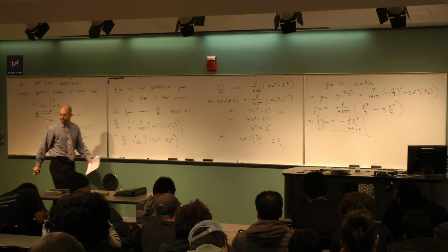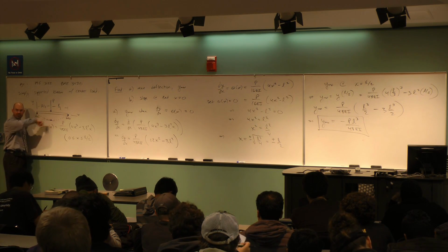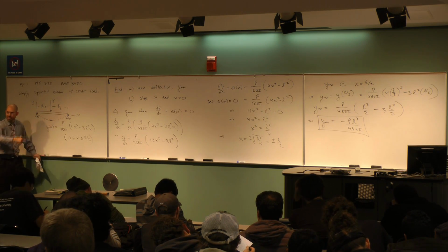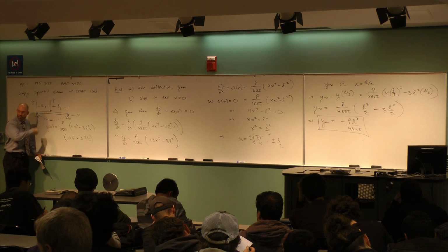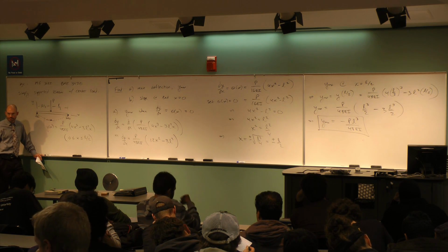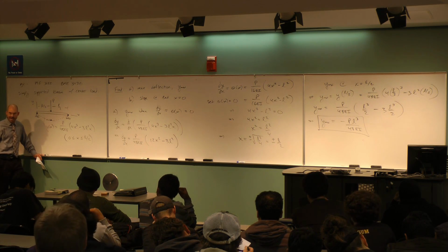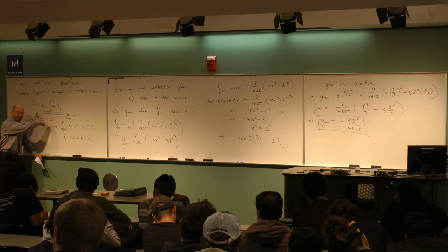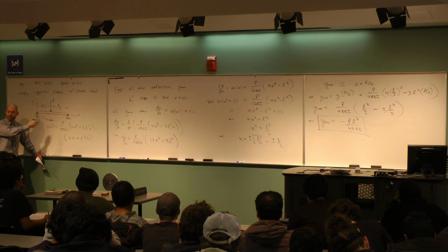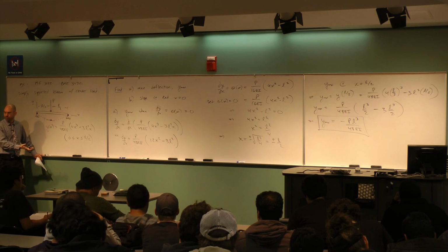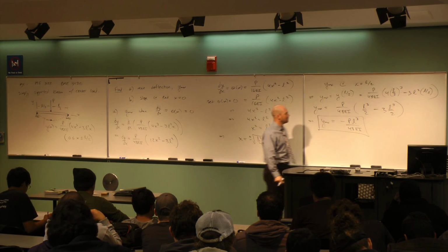Why is that a negative value? Yeah, it's just because of the way I chose the system, right? In fact, in a purely algebraic mathematical sense, that's actually the minimum value of the function. The second derivative here would be what? Positive or negative? Second derivative tells me what about a function? Concavity, and this is concave up. It's a min from an algebraic standpoint, but when I talk about deflection in beams, I mean the biggest overall deflection, right? So the negative, that's why we call that the Y max. Okay. Questions?